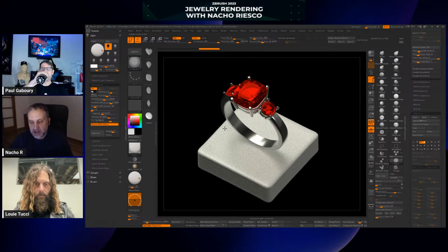So it's not only a matter of material settings. The background and the environment are going to be very important when you are talking about jewelry, because we are always using refractive, shiny surfaces, and it's sometimes very difficult to remove one bright spot that we don't like, that one shadow that we don't like. So it's not a matter of just tweaking the parameters on the material; you should change also the light.